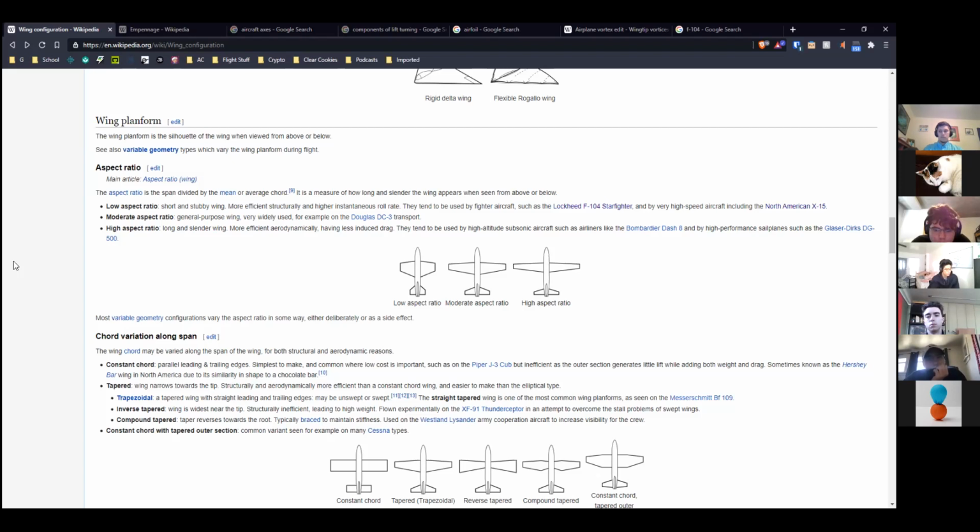But a high aspect ratio wing is also harder to construct well, because you need more structure farther away from the fuselage. So the whole wing can tend to get heavier because the thickness that you need to have enough stuff in there to hold the end of the wing up is greater than it is in a low aspect ratio one.